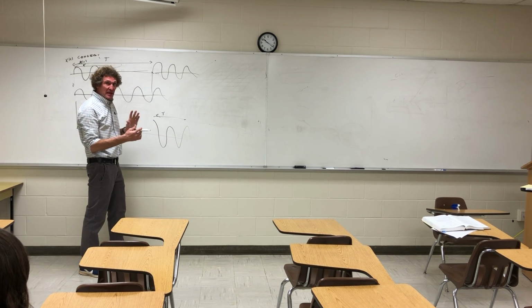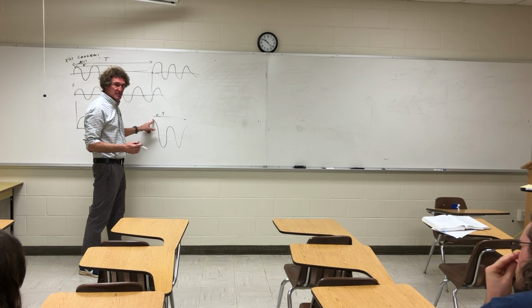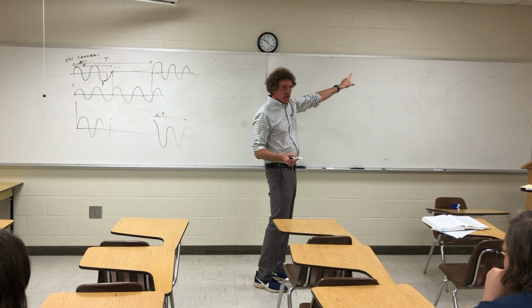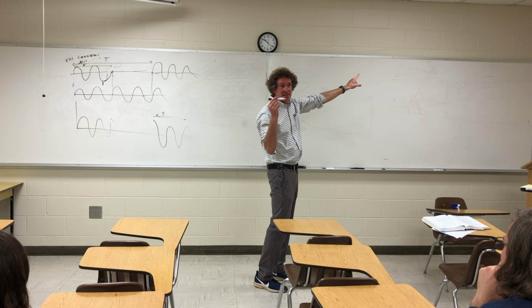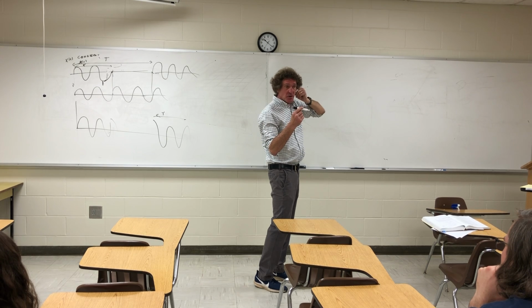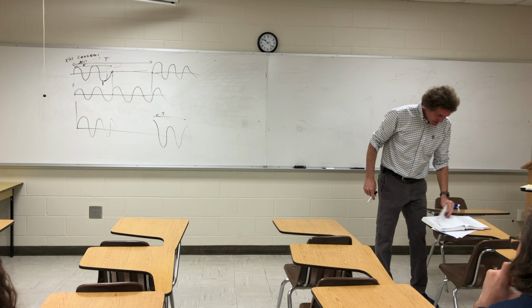All right, but because the phase is different, now when you capture this one back, you can't do coherent signal processing on it. Because remember, I multiplied by the sine of omega naught t and the cosine of omega naught t. That's assuming it's synced perfectly. And I also assume that the theta was 0, right, because it complicates things. Y'all follow me on this class? This is important. At least you get a glimpse of this stuff.